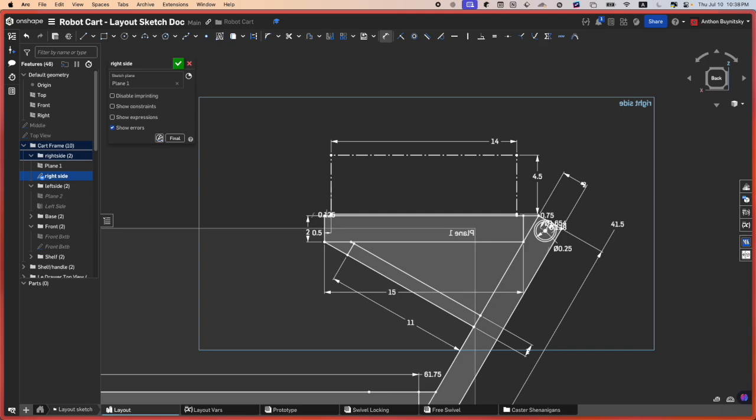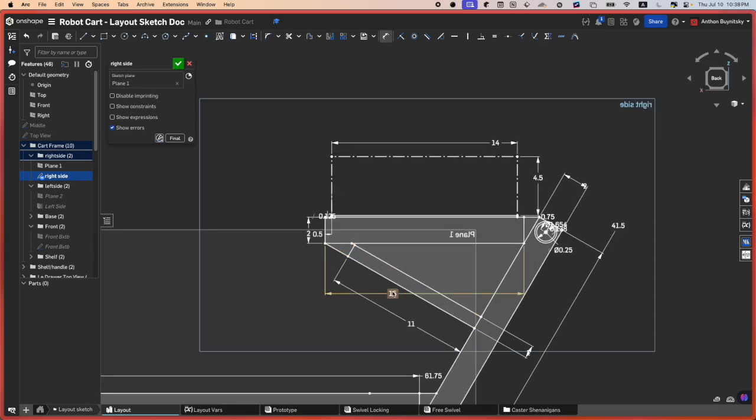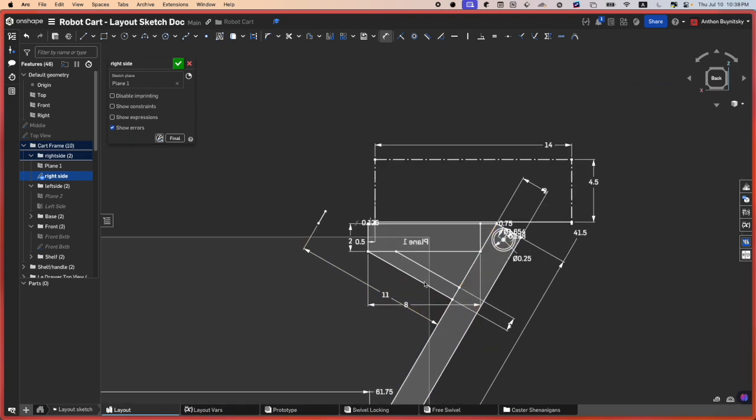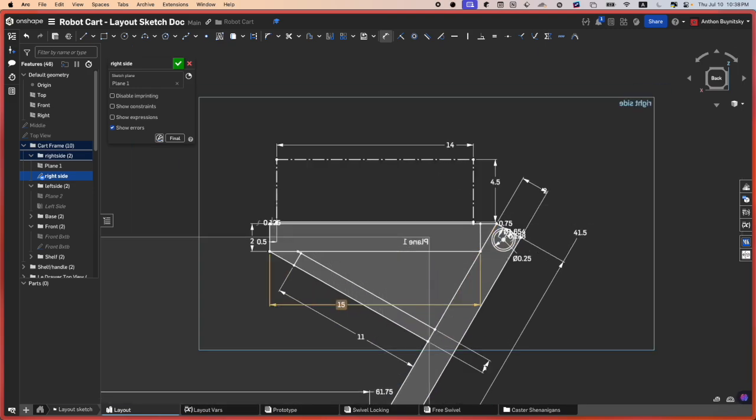So that means, for example, if I made it 20, my gut is telling me that's a bit too long. It protrudes too much on the inside. And if I made it 8, that seems too short. So maybe somewhere in the middle, 15, 16, something like that. And if you generally do not know the dimension, you could ask Raj, you could ask your mentor. And then what you can also do is make this dimension a variable.